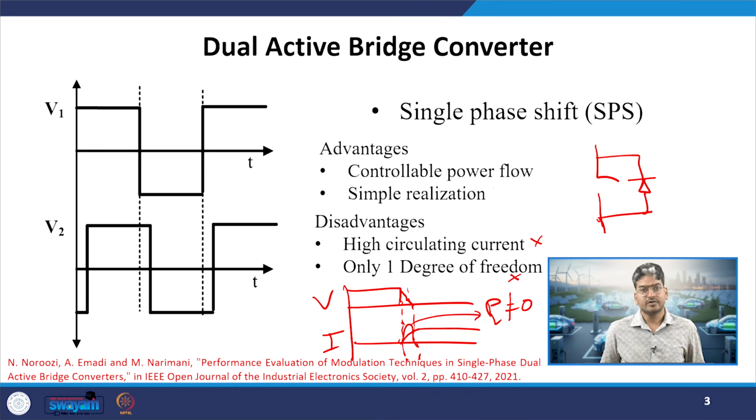If I want to go for soft switching, okay. So, what can be the options? I have to make any one of these two parameters 0 prior to the switching instant. If I make the voltage 0 across the device prior to the switching instant, irrespective of the delay in the current, voltage is 0. So, the power loss will be 0. Similarly, if I ensure that the current will be 0 before the turn on or turn off transition, so irrespective of the voltage drop time or rise time, it will not affect the power loss in the circuit or the power loss will be 0.